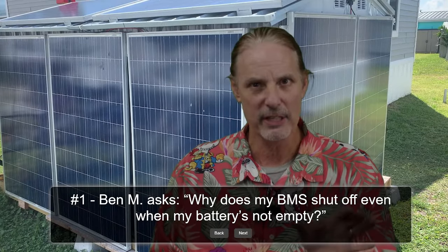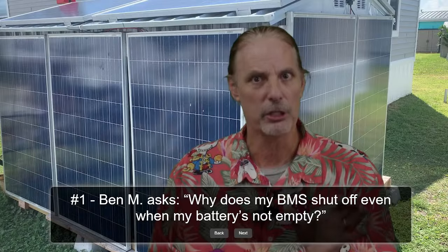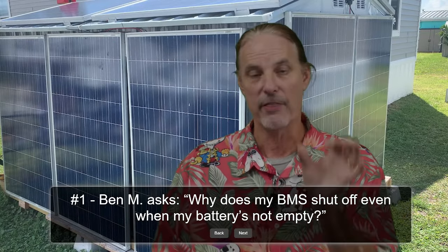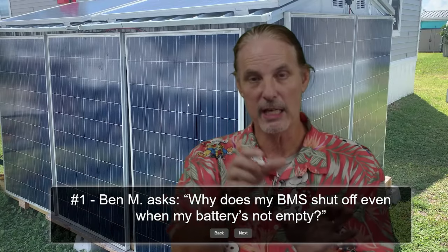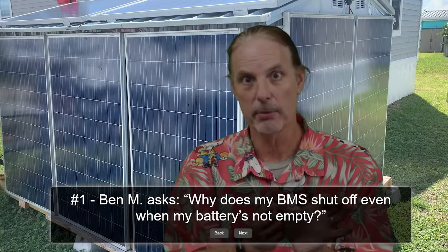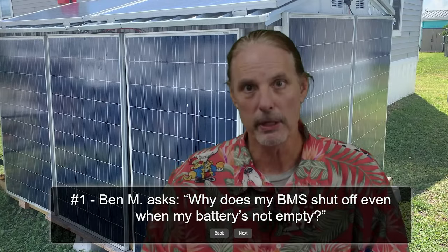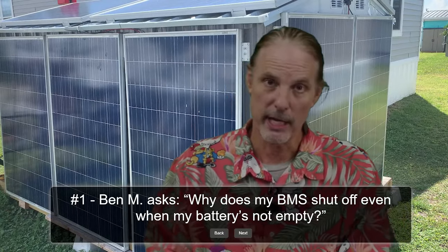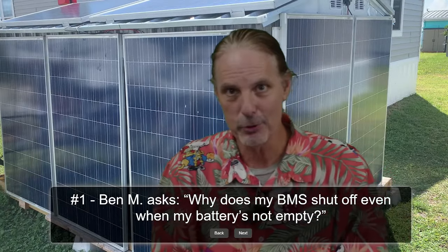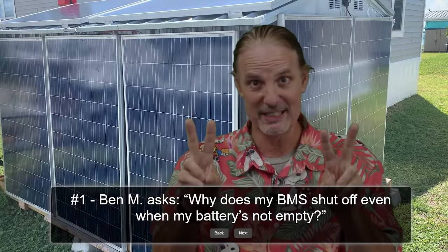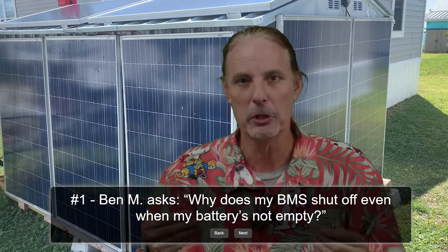I think I have a video out there on calibrating a JK BMS where I check the voltage first, and then you follow that by checking the amperage and calibrating it with a gauge of some kind, and you determine how much amperage is going in. You can't do it in reverse order because the amperage won't be right if the voltage isn't right. So you need both of them to be set for it to really truly be accurate.